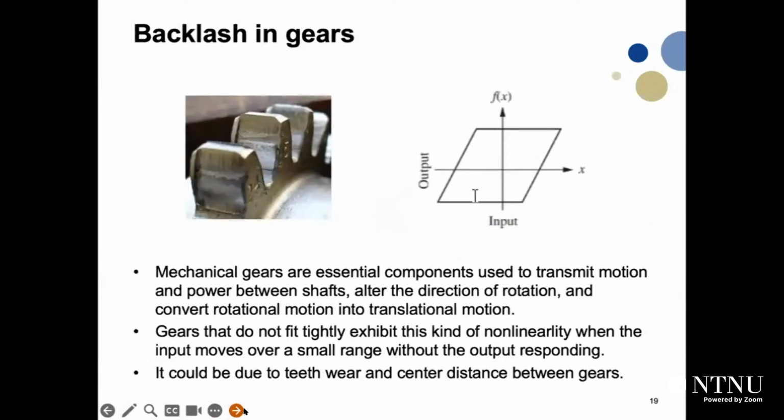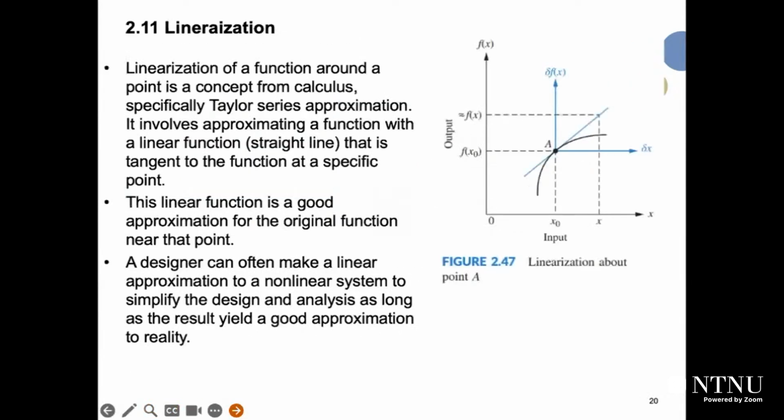Backlash in gears: mechanical gears are essential components used to transmit motion and power between shafts. Gears that don't fit tightly show this kind of non-linearity when the input moves over a small range without the output responding. It could be due to teeth wear and the center distance between gears. So this is a kind of non-linearity.